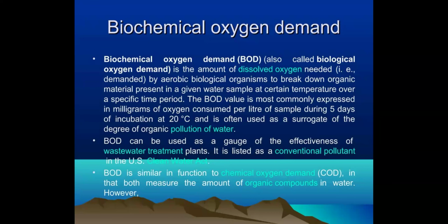The BOD value is most commonly expressed in milligrams of oxygen consumed per liter of sample during 5 days. Most commonly expressed means it will be calculated during 5 days of incubation at 20 degrees Celsius.